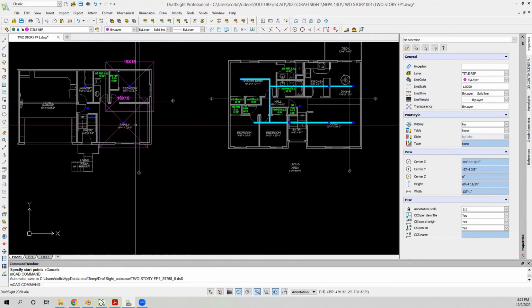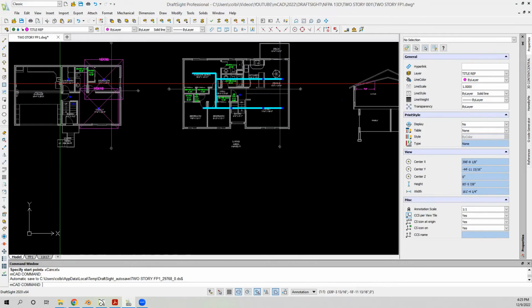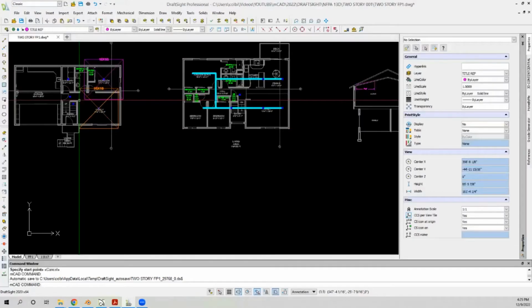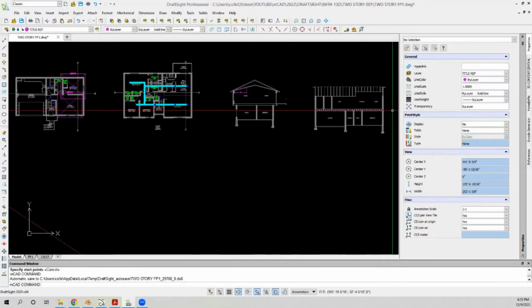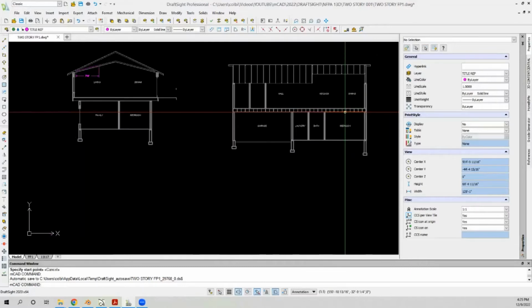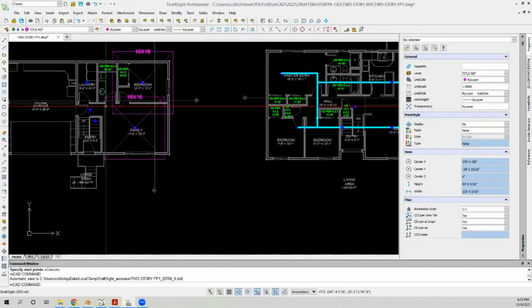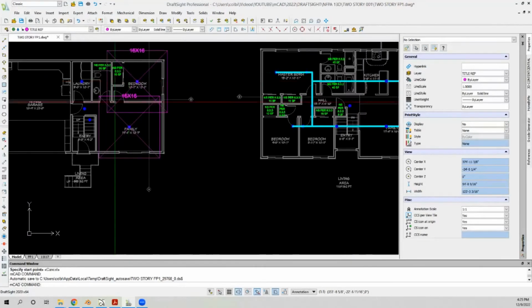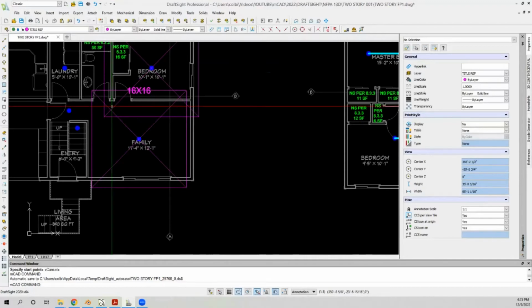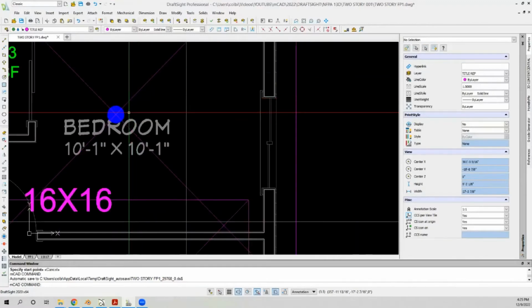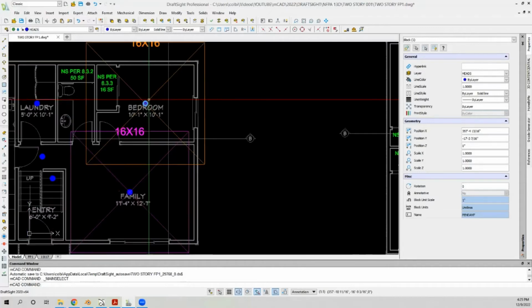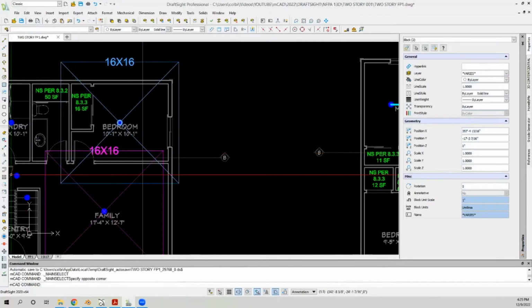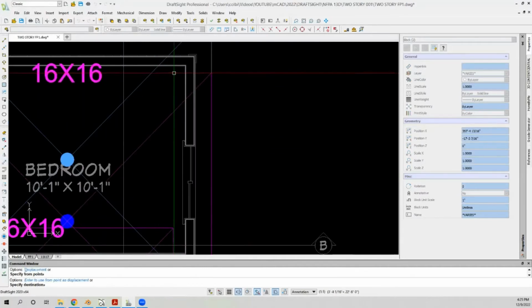Let's go ahead and start laying out our bottom floor piping. We're going to be running this direction with our piping as much as possible. We want to go between these floor joists and kind of minimize our drilling if we can. Some guys don't seem to mind that, and that's totally fine. I like to minimize drilling on jobs if I'm going to install it, because boy, it's just kind of a waste of labor if we can avoid it.